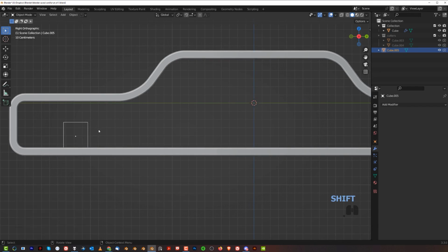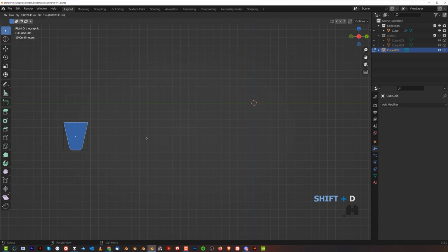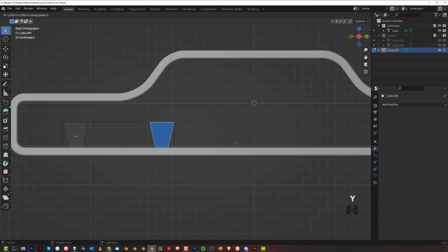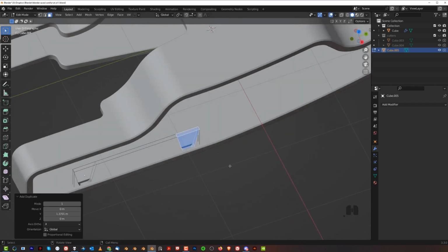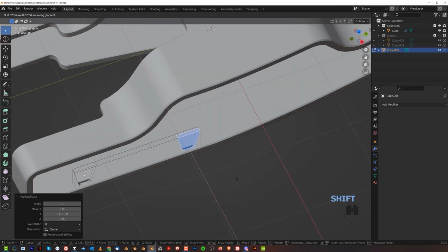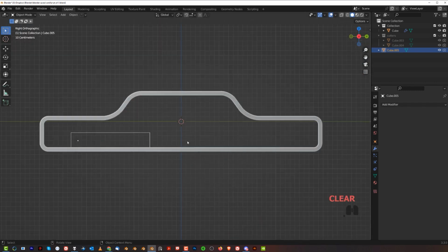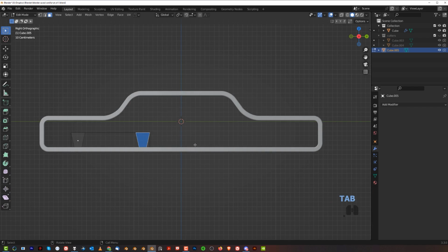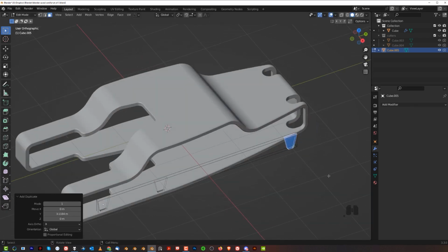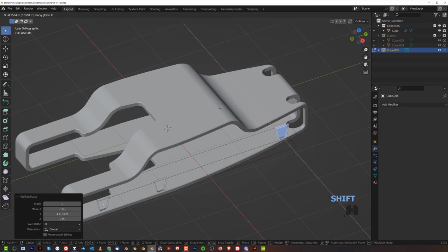So click on this cutter, go to edit mode, press A, Shift D to duplicate it, and just move it here on Y-axis, somewhere maybe here, and we're going to move it a little bit to the right, and do that. And then we're going to copy this one more time, Shift D, Y, and move it to the very front of this shape, and GX, and move it in like this.